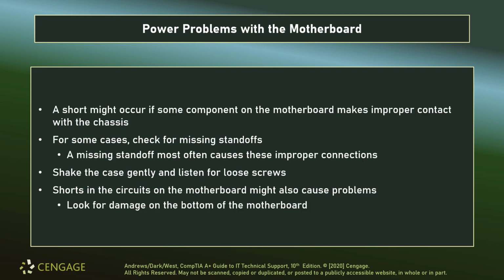Now let's look at some motherboard issues that might come up. Of course, we talked about standoffs and spacers, making sure things were keeping shorts from occurring between the motherboard and the chassis. Take a look at that. Make sure that all of your standoffs are nice and tight, especially if you're switching out your motherboard. Make sure that when you're unscrewing things, you're not also unscrewing the standoffs on accident. Shorts in the circuits on the motherboard could also cause problems. Make sure that if there's something that happens on the underside, that you're able to identify it. You may also want to check and make sure there's not loose components that get trapped underneath the motherboard against the chassis, which could cause a short.